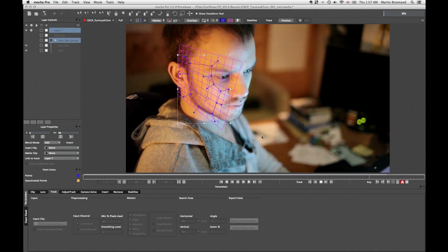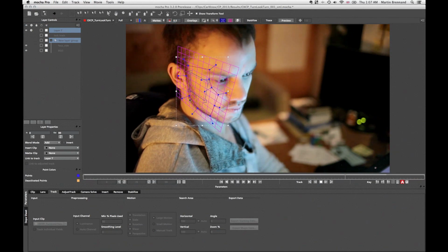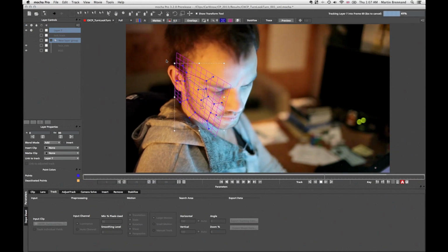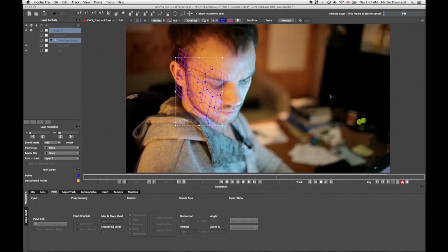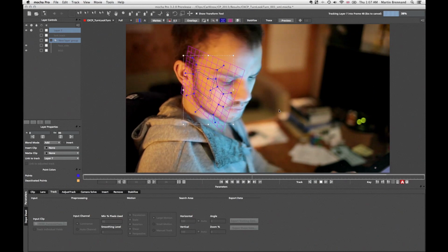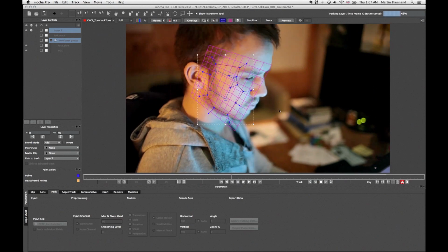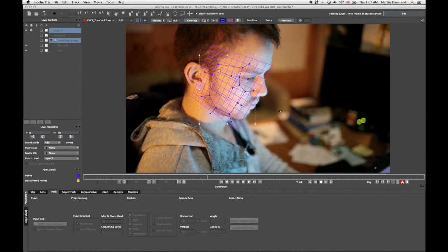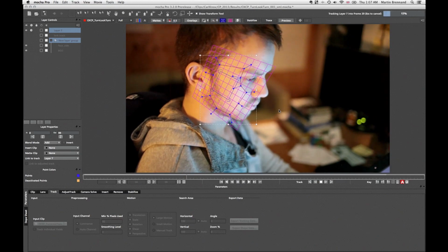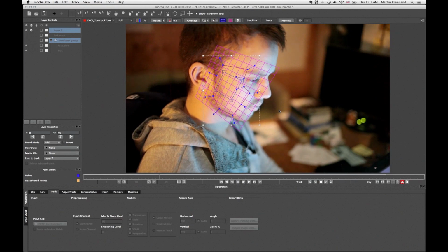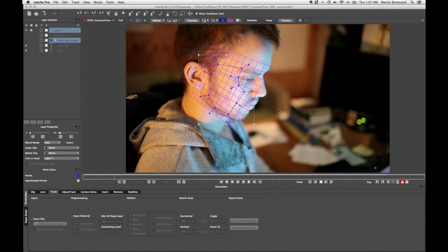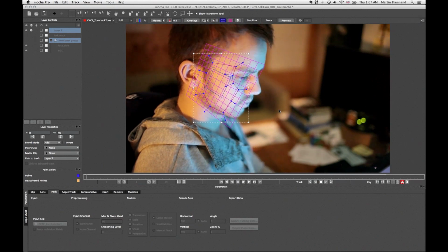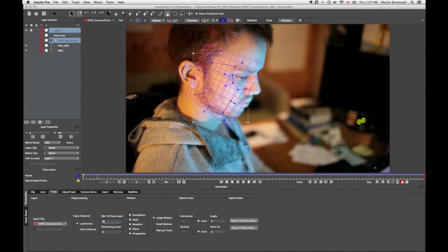So what we're doing here is, instead of getting the static areas of the shot relative to the camera, we're getting the moving objects relative to the camera. Now, the way we do this is that, first of all, we have to solve the static shot. We still have to tell Mocha there's a camera sitting in this scene. So we need to solve those static areas before we solve moving areas. Because if we try and solve moving areas first, the solver will assume that you're actually solving with static areas and you won't get the camera that you're after. So we'll just track that, like so.